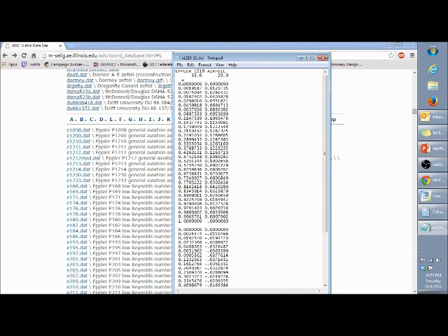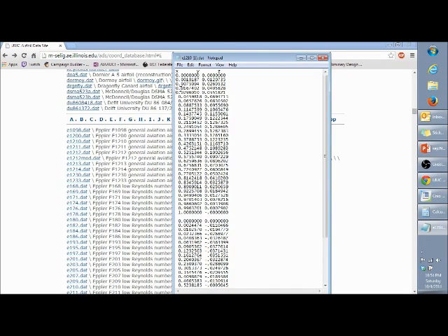First off, you'll want to delete these first two lines, and you'll put X, tab, Y, tab, C. And an important note, because Pro E will freak out and will not let you create the points to create the airfoil, is that these right here are spaces. What you want to do is delete these spaces for all your points, and it's pretty tedious.